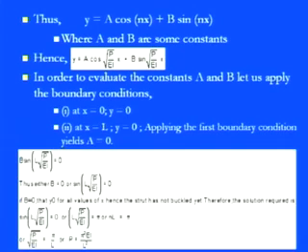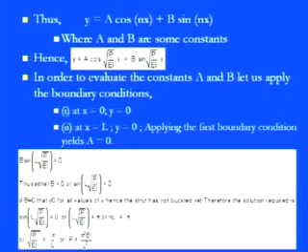Because we initially assumed there is no change in the dimension and the strut is straight, there is no worth in keeping B equal to 0. So obviously the other term must be 0, so we have sine of the whole term equal to 0, so L times square root of P over EI is equal to pi, or in general n pi. So square root of P over EI equals pi by L, or we can say the load at the buckling point is equal to pi squared EI over L squared.